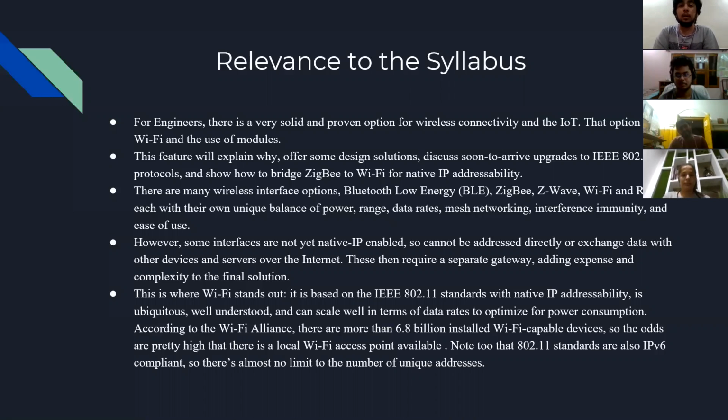with an Arduino. The Arduino circuit is the one which will control the door, and in order to communicate with a computer vision algorithm, that is a machine learning algorithm, which will be used to recognize the face of the user and to verify whether the person trying to open the door is the correct person or not. We'll be communicating between these two modules, the Arduino module and the machine learning module, using a cloud platform, which is ThingSpeak.